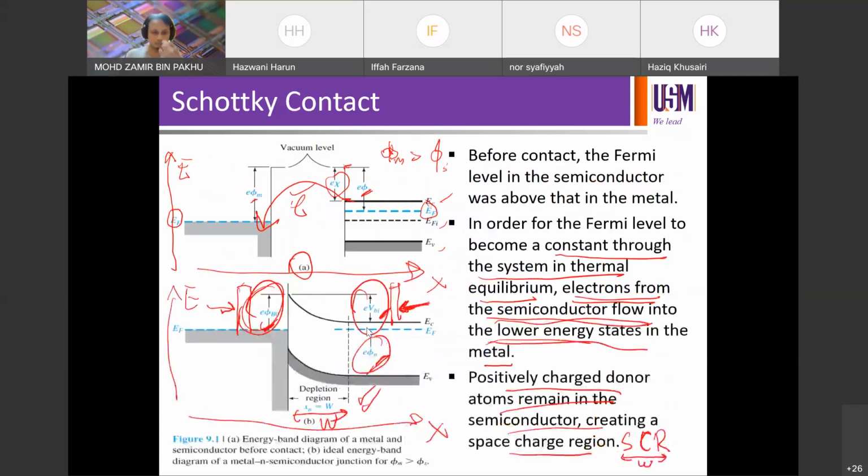If you look at this curve again, this is the band diagram here. Before this, we've been talking about a single VBI in PN junction, and this is two potential barriers, and VBI is on the semiconductor side. So proportional to ln ND, yes, it is.